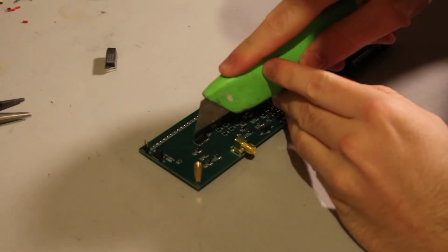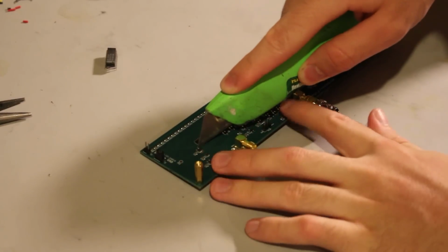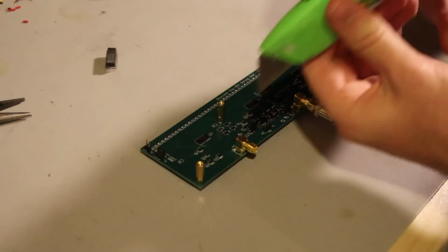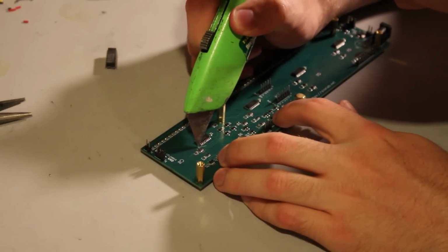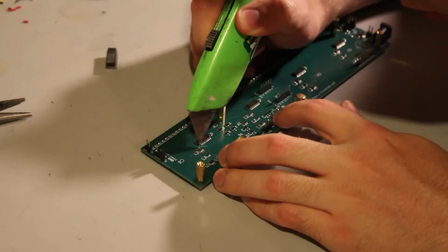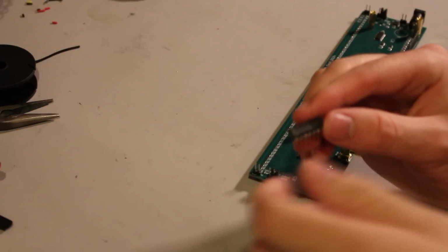I had to go back and find a bunch of these tiny issues with my hot plate soldering, which is weird since hot plate soldering is usually the easy part. Nothing wrong with JLC PCB services, I think I just went a bit light on the solder paste in a few spots. After resoldering loose joints and disconnecting a couple of shorted joints, the board worked.